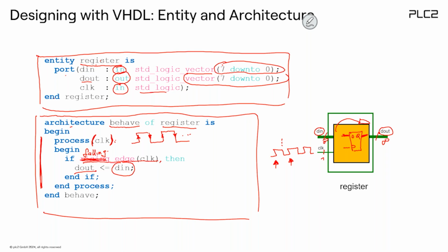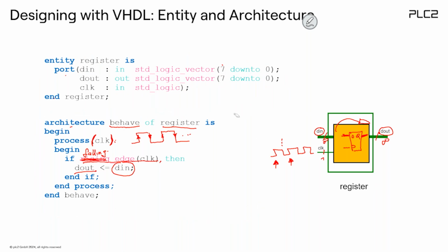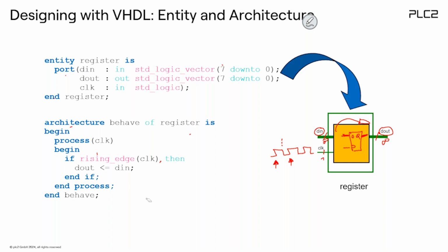This means these are the basic design units used in our FPGA VHDL design. Entity describes how the block looks from the outside world, and the architecture defines what is inside. And these always belong together. And now you see the design units as entity and architecture.